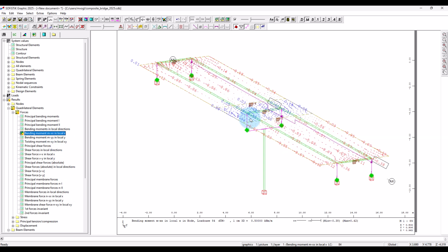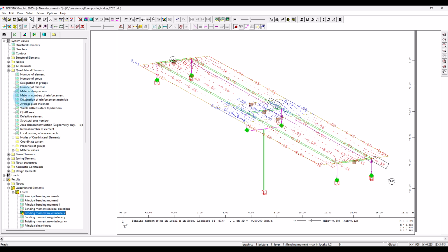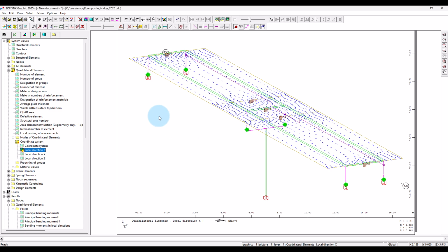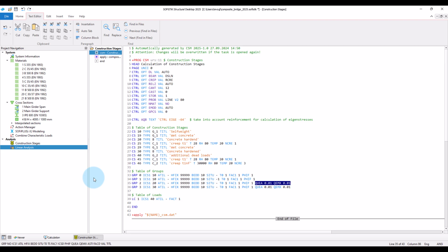Same for the bending moment, MXX. Okay, I will also shortly check the X direction to be 100% sure. Yeah, okay, worked as it should. So temperature and settlement loads accomplished. Now, as next step, we can go to the traffic loads.